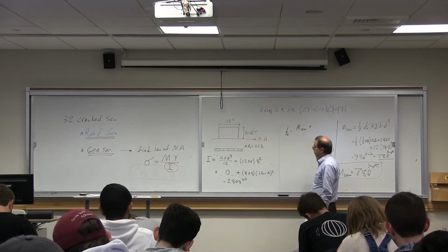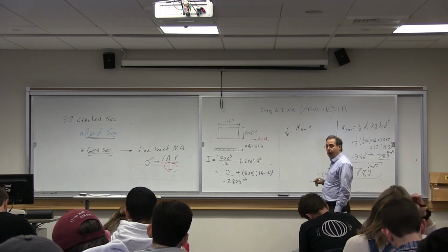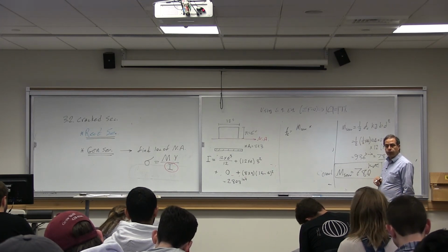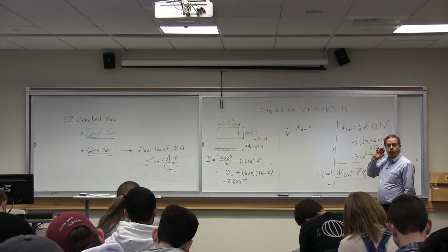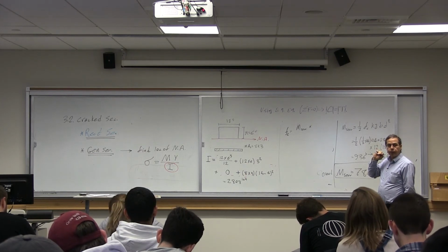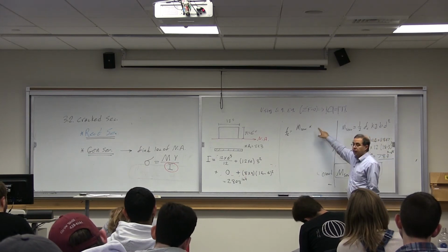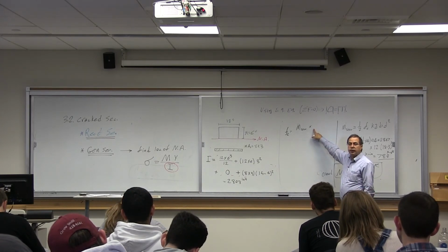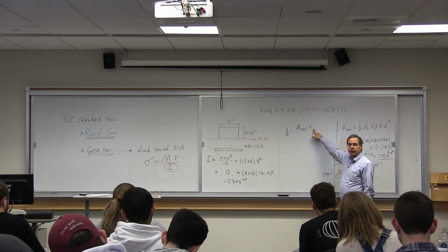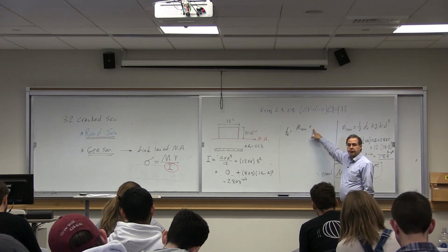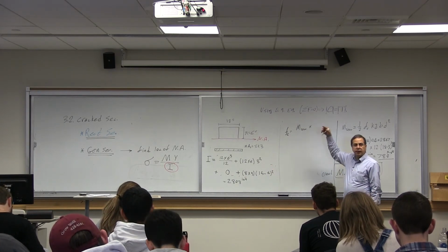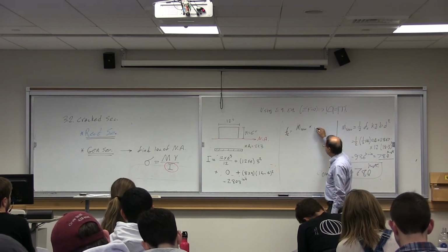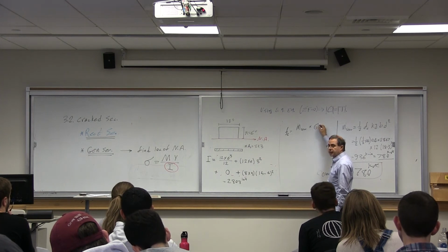What would be Y for concrete? What number should I put here? Six. That's the distance between the centroid and wherever you want to calculate the stress.